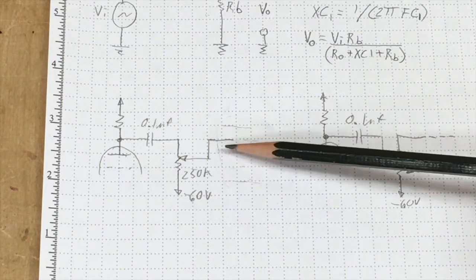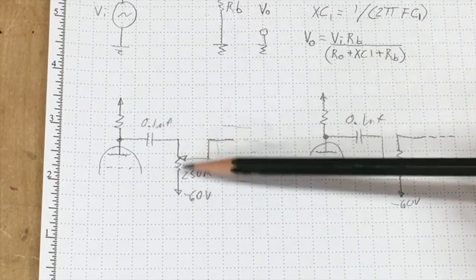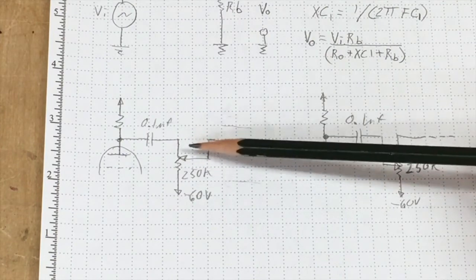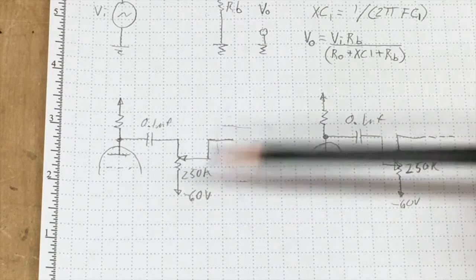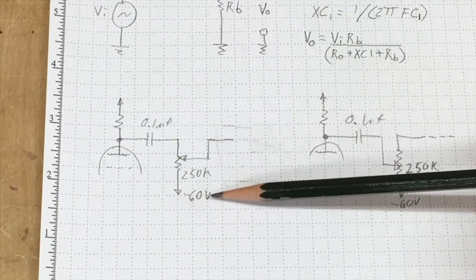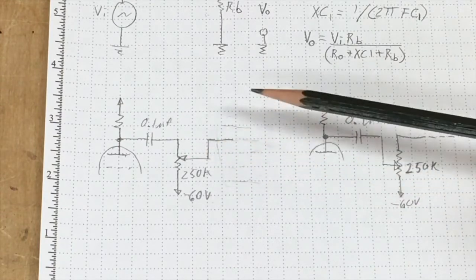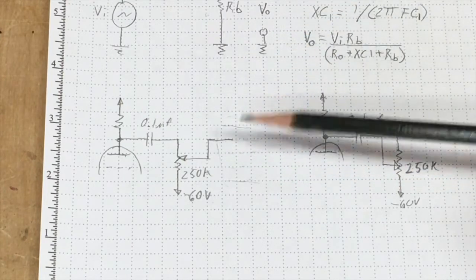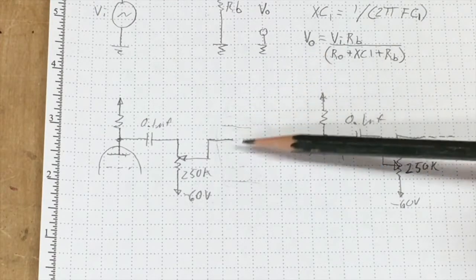I don't like this, and here's why. First, this potentiometer is a physical device. It gets churned all the time, and eventually potentiometers fail, which means that the connection between the wiper and the legs of the pot will eventually degrade. That means your minus 60 bias voltage that you're trying to feed to your output tube will change and possibly become interrupted, which is a big problem in a fixed bias amplifier. It's the only thing keeping the output stage stable.